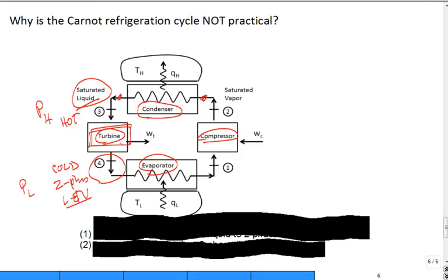What's the next one? It's about the compressor. What type of compressors do you like to buy? What do they like to ingest into them? What do they not like to ingest into a compressor? They do not want any liquids. No fraction of liquid in the mixture going into it. So they want vapor, or gases, to go into a compressor. So those are the two things.